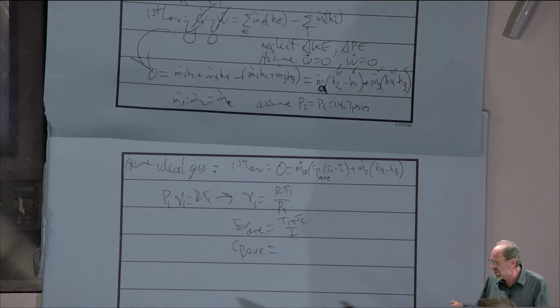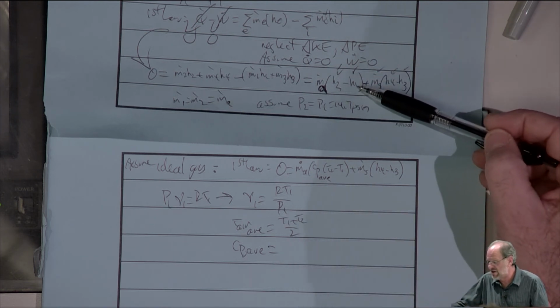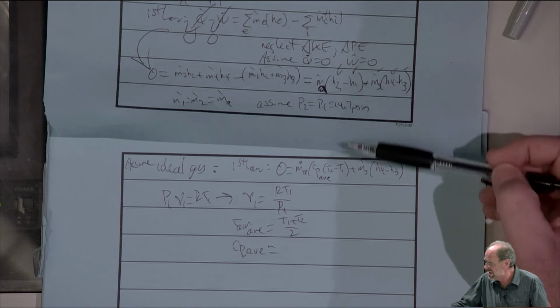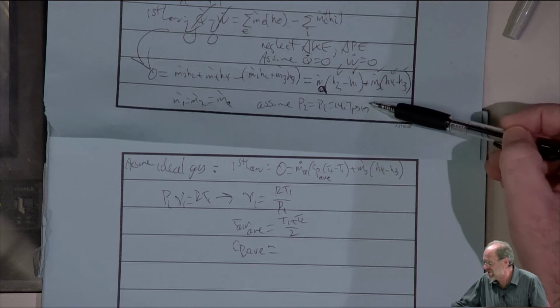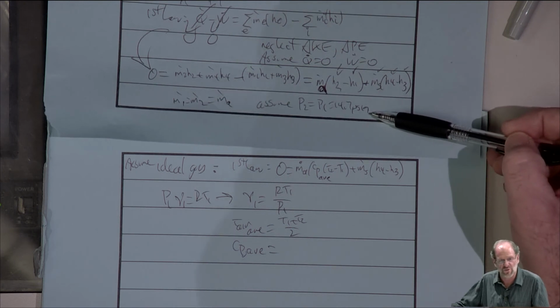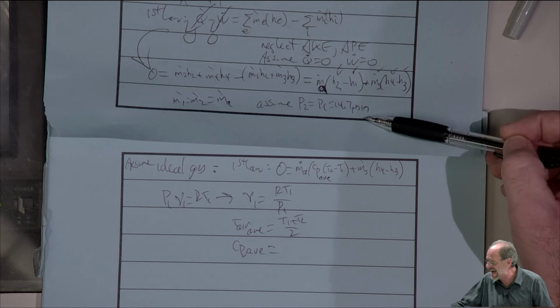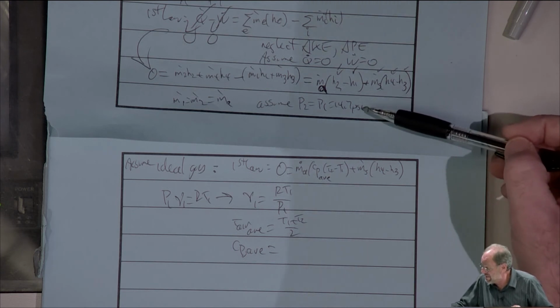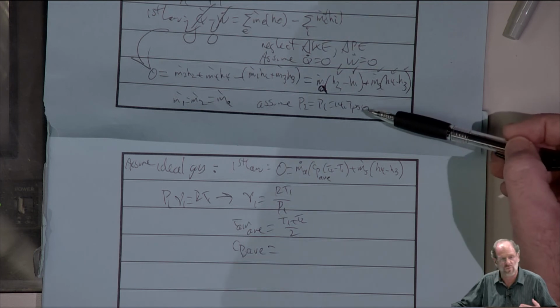One other thing I might want to note: since we've used the ideal gas assumption and we're not using enthalpy change directly, but Cp times temperature change, all that I described before about assuming the pressure is constant doesn't even matter. We know that for ideal gases, the properties of enthalpy and internal energy are strong functions of temperature, but very weak functions of pressure.